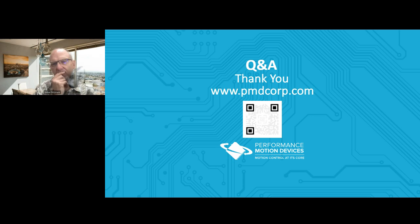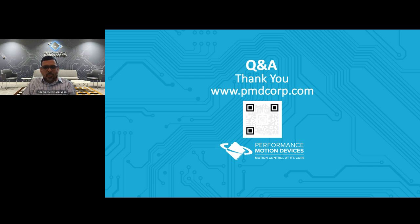Interesting. So in that particular case, with EtherCAT, obviously it has the distributed clock, right? It has the DC synchronization. So the EtherCAT packet itself has the synchronization. It's not a separate signal. So in our chips, if you do your own board design, there's a separate sync signal that goes between the chips to synchronize them. In the EtherCAT application, it'll be on the packet that comes across. You still need one of the nodes to be the timing master. It has to have a really good clock that everyone can time off. So our next gen product would have native EtherCAT on the drive.